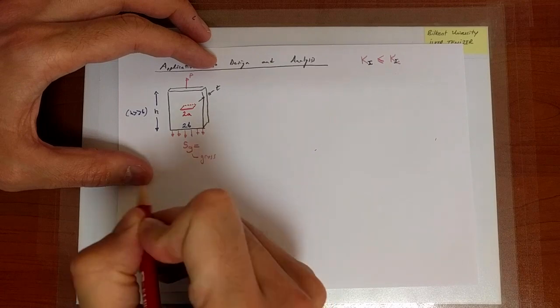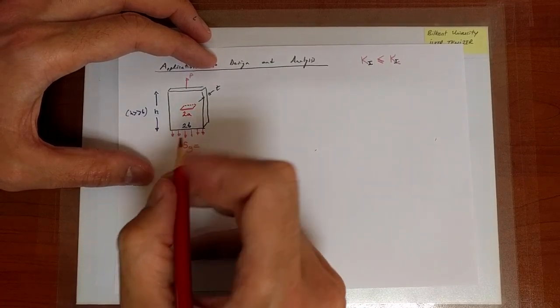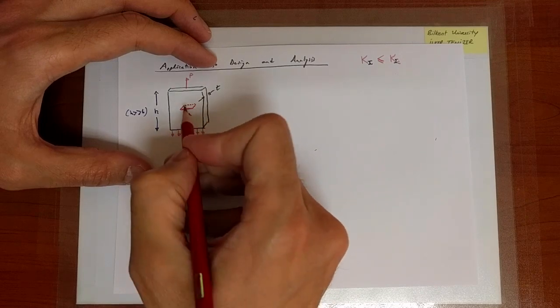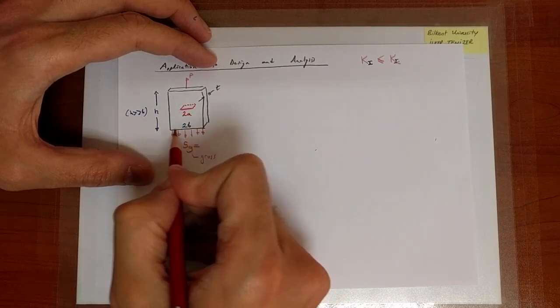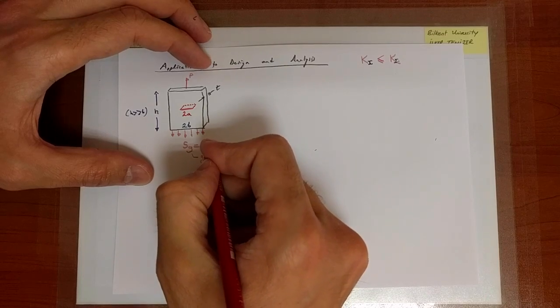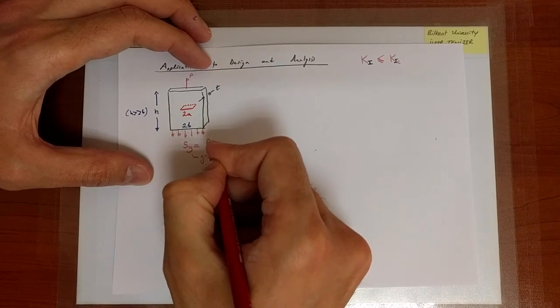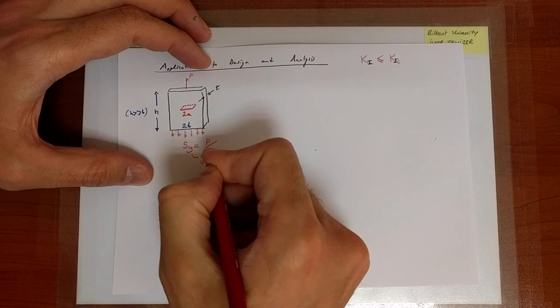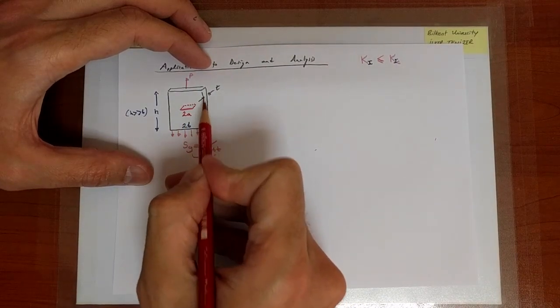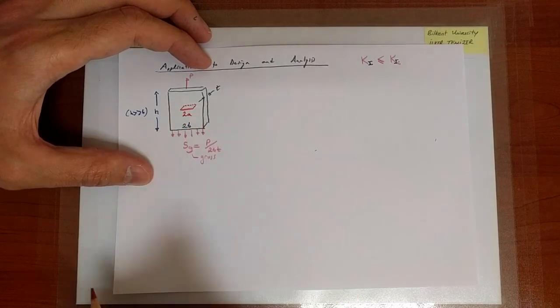SG is consistent with our very first definition, where we assumed that the crack was very small, or essentially we were looking very far away from the point of the presence of the crack. We said the stress is P divided by the cross-sectional area, which is in this case 2bt, the width times the thickness.